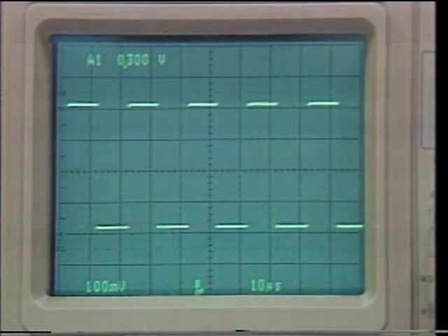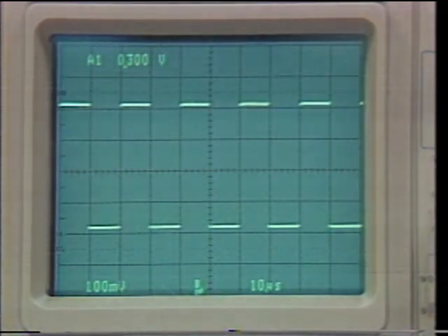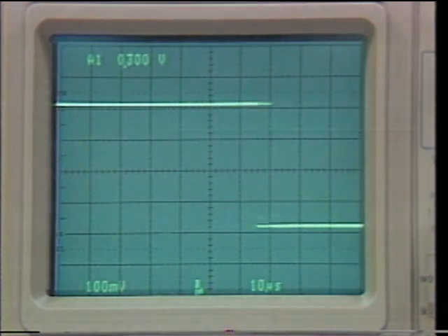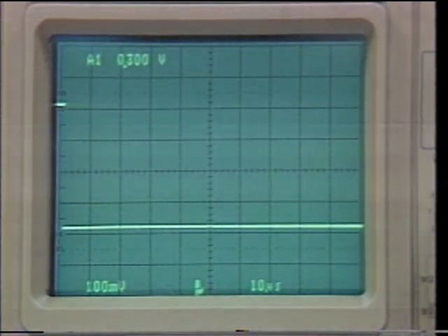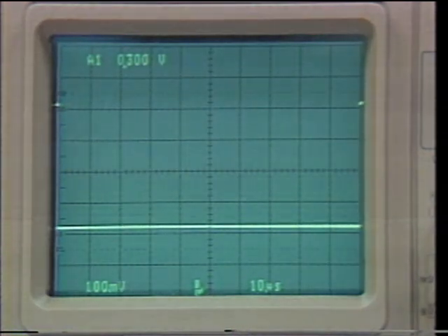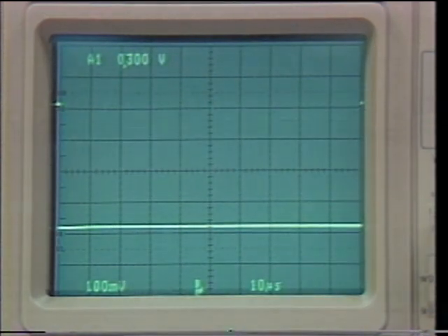The calibrator is also adequate to verify the magnifier. We turn on the times 10 magnifier at a moderate speed so that we're not seeing the transition time of the signal. 1/2 cycle of the calibrator should be exactly 10 divisions. And if we look carefully, we can see that it is. If there's any doubt about the symmetry of the waveform, which there shouldn't be, we can look at both half cycles and observe that either half cycle gives us very nearly 10 divisions.